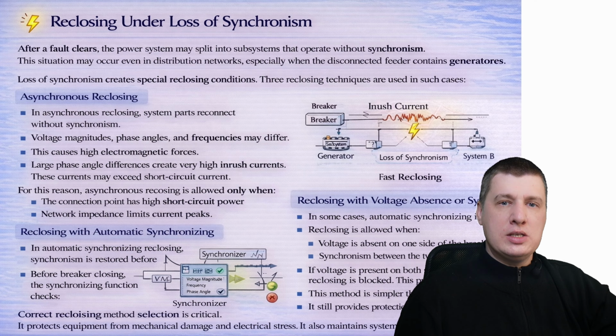In asynchronous reclosing, the system part reconnects without synchronism. Voltage magnitudes, phase angles, and the frequency may differ. This causes high electromagnetic forces. Large phase angle differences create very high inrush currents. These currents may exceed a short circuit current.